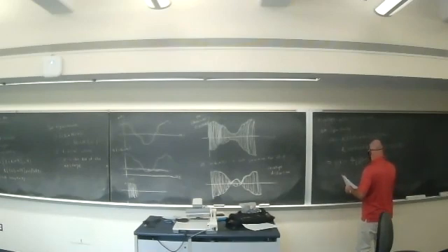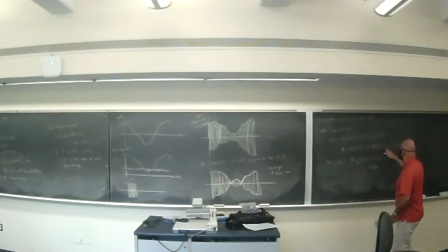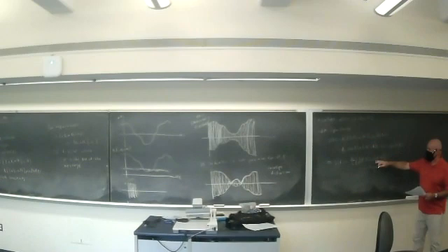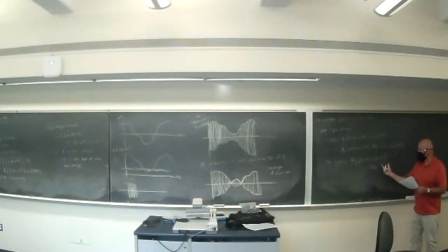And Ac Ka over 2. This becomes m(t) times cosine. That's multiplication in the time domain. That becomes convolution in the frequency domain. But we're convolving with a pair of impulses. Okay. This is the Fourier transform of the cosine part. So this will become M(f) convolved with this.